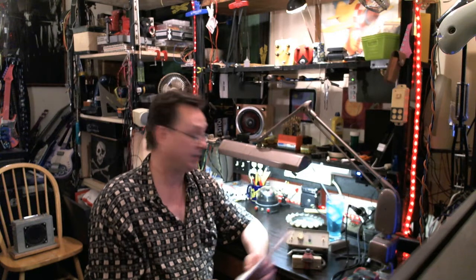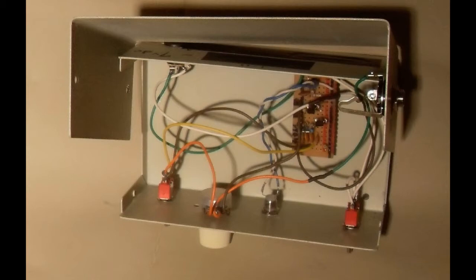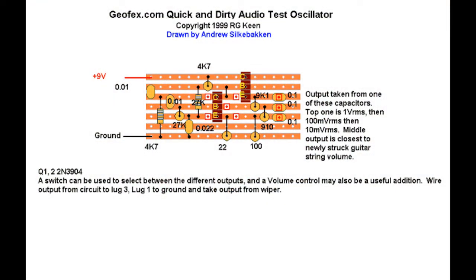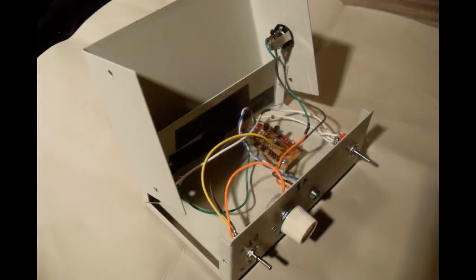So like I said, it's for audio and effects testing. You could use this device to troubleshoot broken down audio equipment. It's not just for guitar pedals. It's a real basic circuit. There's not that many parts. It uses a 2N3904 transistor, Radio Shack part number 276-2016. They're $1.19. There are 7 resistors and 6 capacitors. There's a 0.022, 0.01, and a 1, and those are non-polarized, like little Mylar orangey buddies. You could use those.